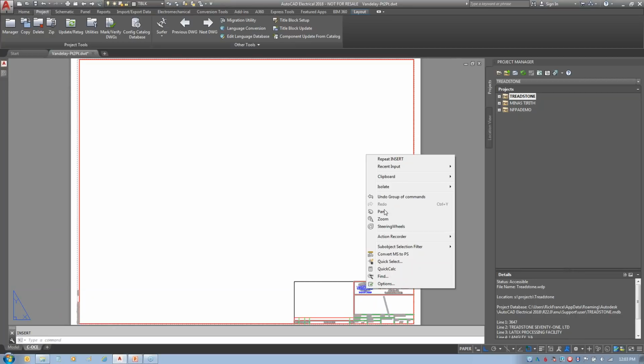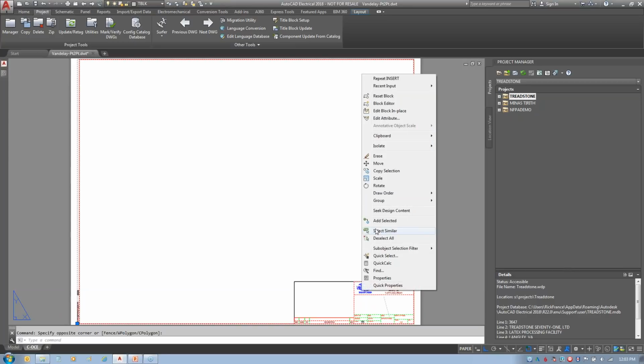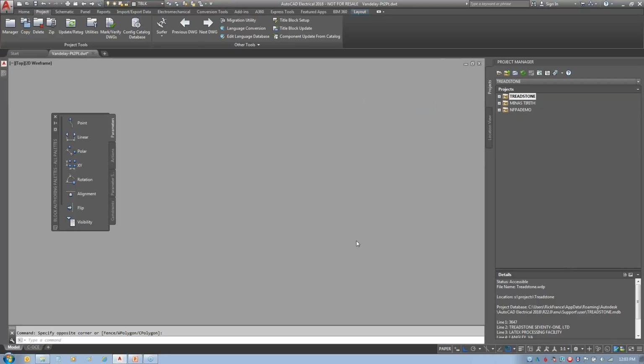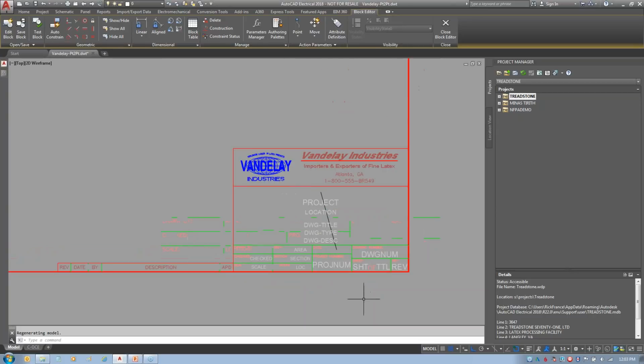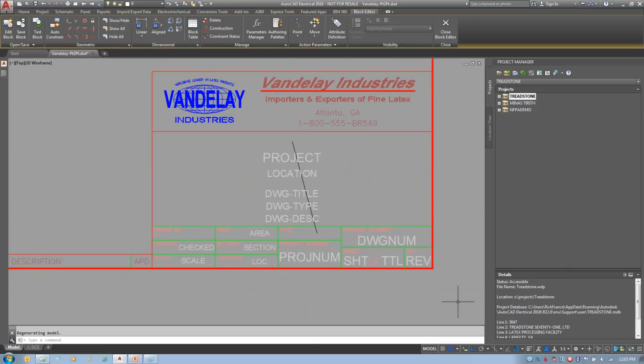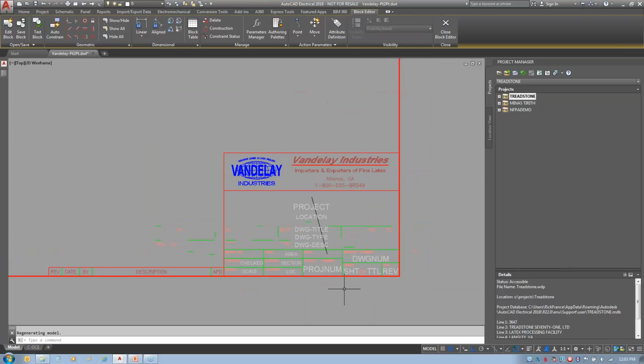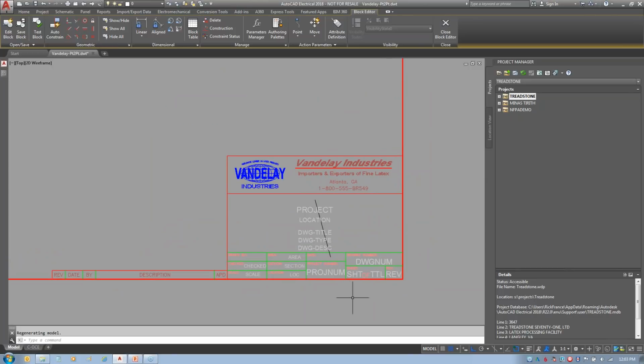So I'm going to open this up in AutoCAD's block editor. Close the dynamic, because it doesn't need to be dynamic or anything, and zoom in here. That line going through my text is only there to make it a little faster during the webinar for me to place a couple of attributes here. Basically, I use paper space, so I don't have to worry about annotative scale in my title block, because I use paper space with a viewport, but a lot of people don't.